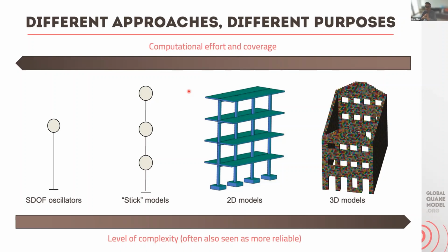I just want to mention that from using many of these 3D models and reviewing many of these 3D models, I would say that having a more complex model does not necessarily mean that your model is more reliable, because then you also open a bunch of other problems related to how you calibrate these numerical models, and how you collect the geometric, the mechanical, and the dynamic properties of some of these models. So it's not just the computational effort, there is also a lack of a lot of data that is necessary to properly calibrate these models.